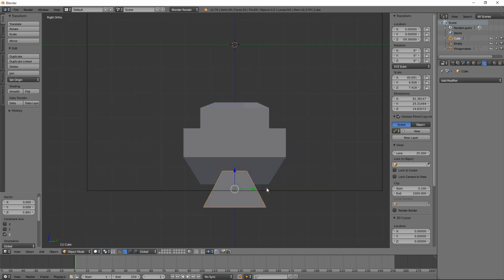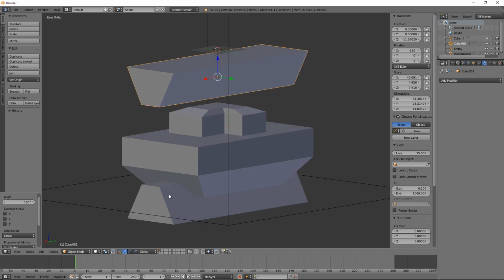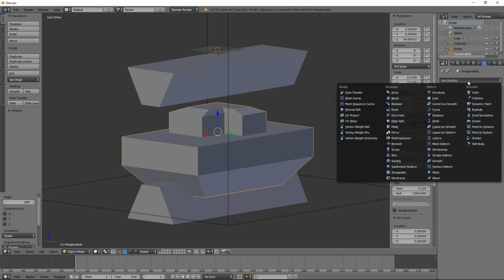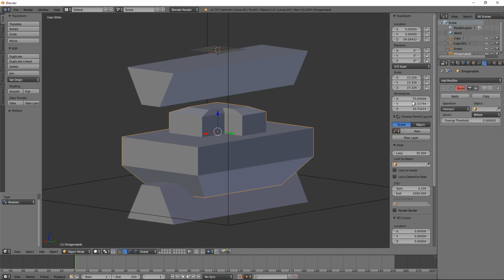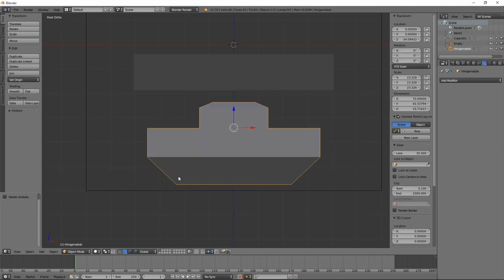You know what else I'm going to do? I kind of like the shape of this. I'm going to hit Shift D, and we duplicate it. I've got it right now, and he's moving free. I want to move him up along the Z-axis, so I hit Z, and I'll rotate him, and I'm going to hold down Control while I rotate him with that R so that he flips over nice and evenly. We'll use him in a second. This guy, we're going to do another Boolean difference on that object. Good enough. We'll delete that. Huh, I could have just kept it. So there's that. Good stuff.